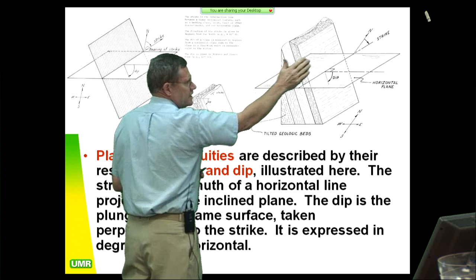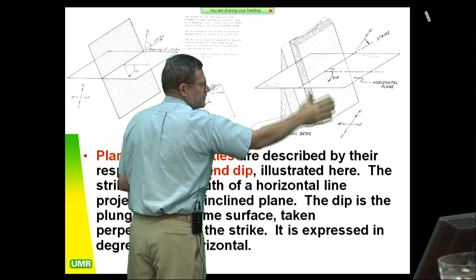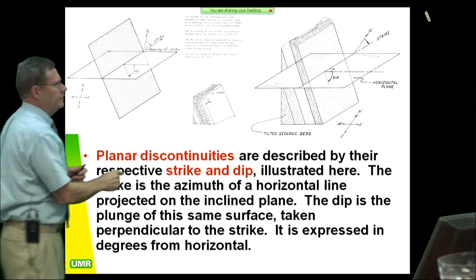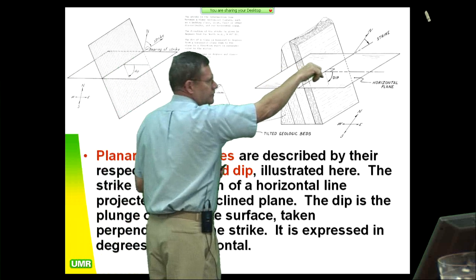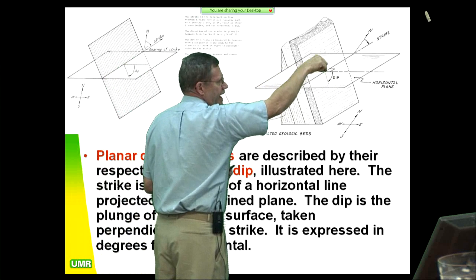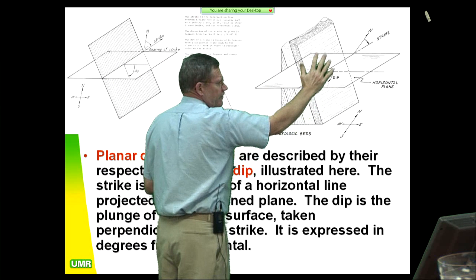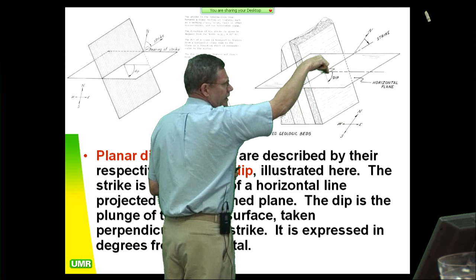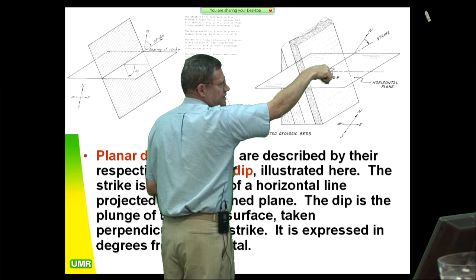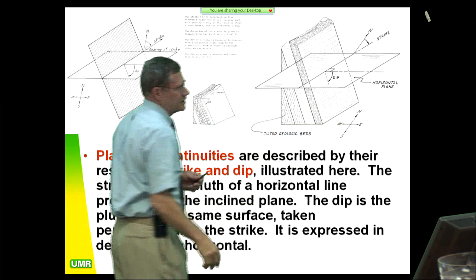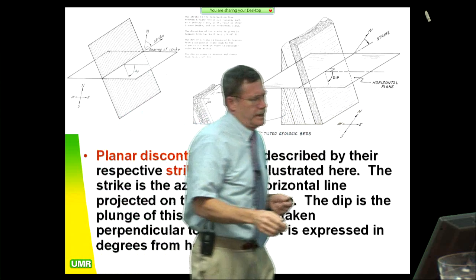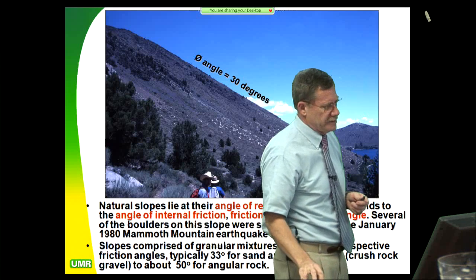So this would be one discontinuity suite, the bedding, and then the plunge of the dip is going to be the maximum line. Now, when you have movements, they very rarely go right down the dip. Usually they have some apparent component going off this direction or off that direction, depending where your road cut or wherever your cut slope is.